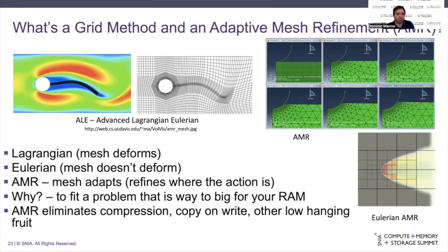So often applications use squares or cubes, likely polyhedrals, to represent a cell in which a single value of all the state array lives. Apps often use something we call AMR, adaptive mesh refinement, to be able to run through a larger problem than will actually fit physically in memory of the system. And they want to run this at full resolution. So through the simulation, the resolution is changed. They kind of drill into interesting parts of the simulation and kind of zoom out of the uninteresting parts from in different time periods throughout the simulation when something more interesting starts happening. And this can happen every few, or in the most complex case, every single time step.